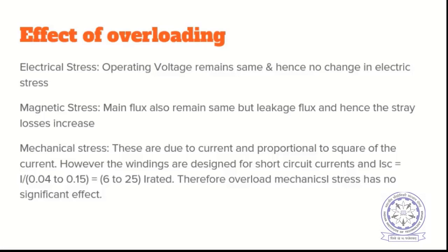increase in electric field in any part of the transformer, because when you design a transformer you have to take care what are the electric fields inside the transformer, and with that electric field what is the effect of aging or effect of breakdown or whatever it is. So the electric field design has to be taken care inside the transformer, and at the edges or where the end points are, joints where you are joining the leads to the bushings. So there it should not happen that the electric stress increases due to overloading.